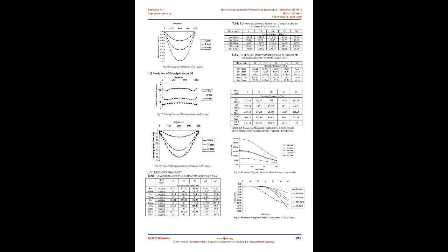Fig 7. Skew slab showing various regions. The following bending stresses were considered for the 8 m 2-lane bridge to find out the maximum design moments. 1. Stresses parallel to the central line, parallel to the x-axis, SX. 2. Stresses parallel to the supports, SZ. 3. Stresses perpendicular to the supports, SY. 4. Principal stresses S1 and S2 given by ANSYS.